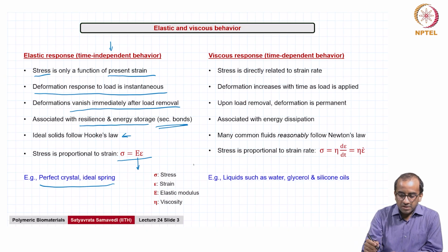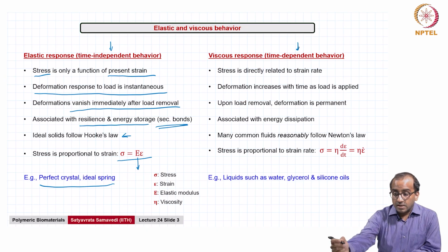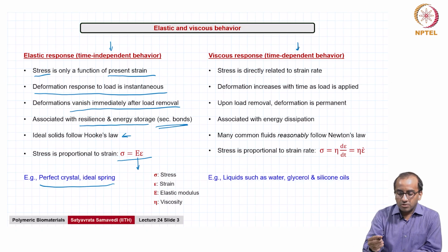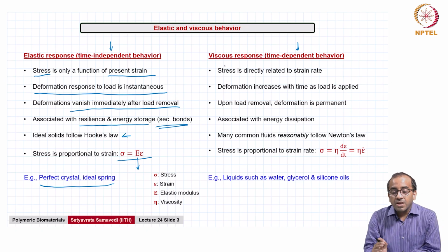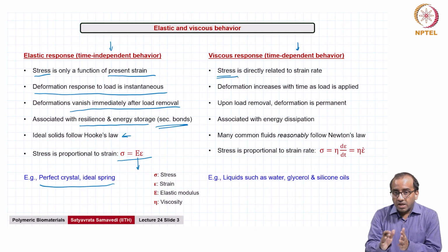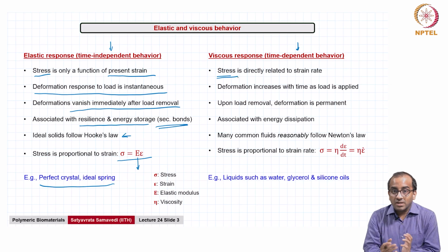Now, viscous responses, like I said, represent time dependent behavior. These are purely viscous responses, where when you apply a load or a stress on a purely viscous fluid, the molecules are anyway moving around randomly, and they will move past each other. You can't really lock in, quote unquote, the deformation when you apply a load. So deformation per se is not so meaningful to talk about for a purely viscous system, rather it is the rate of deformation that actually matters.